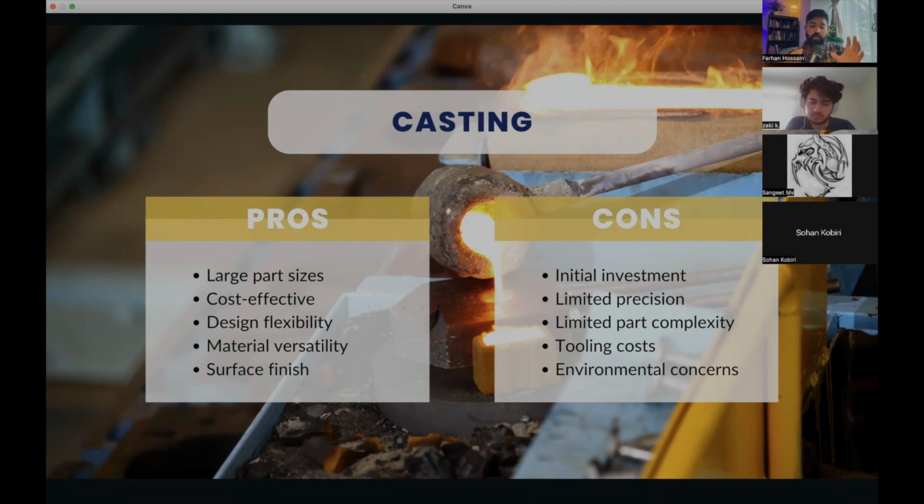So for example, let's just say you have this bowl shaped 3D part that you want to make out of metal, right? If you CNC it, it's going to take forever. But let's just say you cast it to roughly the right shape, and then you come and post CNC it to make it more beautiful or finished. That saves a lot of time and money because you waste less material because it's closer to the net shape, we call it, and you use the CNC to finish it, and it runs only for like half the time or quarter of the time.